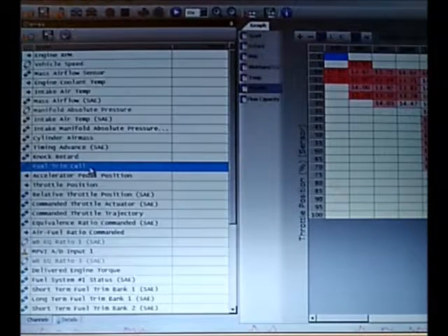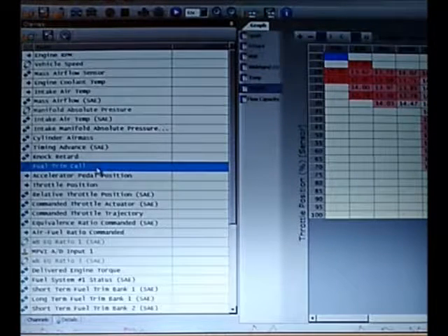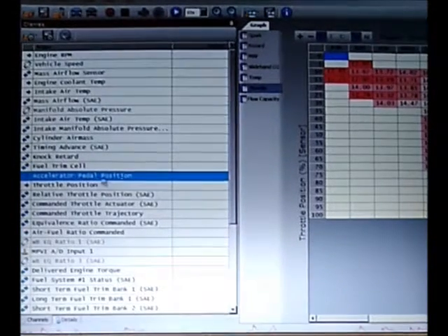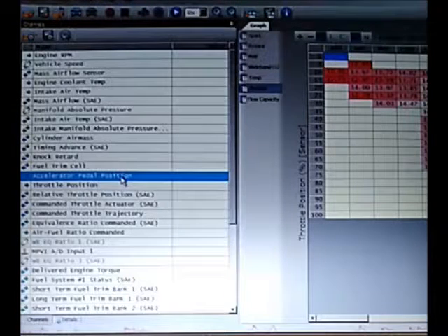So it'll just cancel out every piece of data that goes into a certain area of the VE table. And I don't really want to do that because there's a chance that some of that data might be good, and there's a chance that bad data might fall in other parts of the table. So I'd rather just specify the parameters myself rather than let the computer decide what it thinks. Accelerator pedal position, you're going to need this to do your filtering.